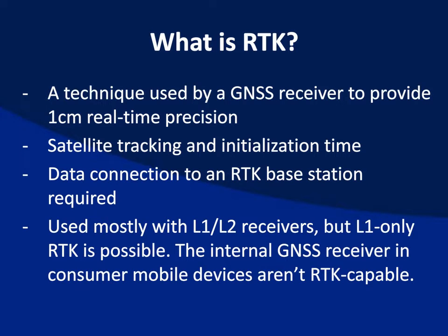And then the third thing, this third item on this slide, is the data connection to an RTK base station. That is really, really critical. You need to have a reliable data connection. It doesn't have to be a high bandwidth data connection. It doesn't take a lot of data, but it's got to be really, really reliable.